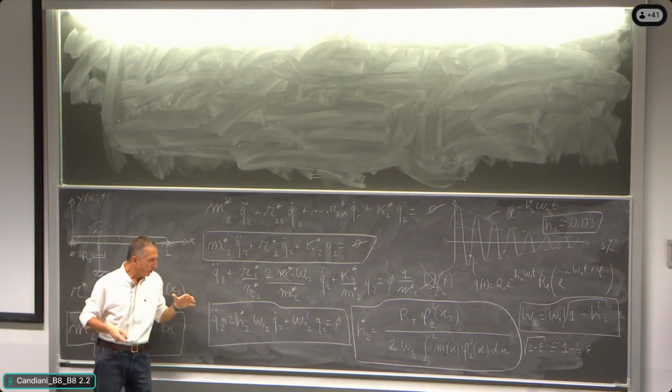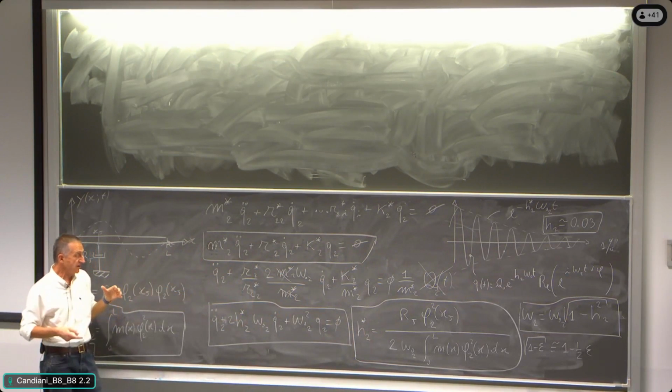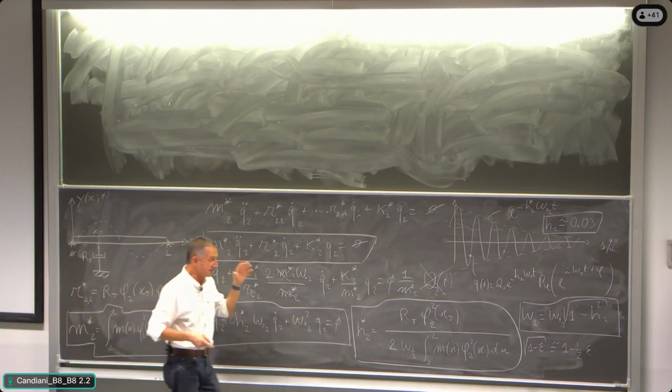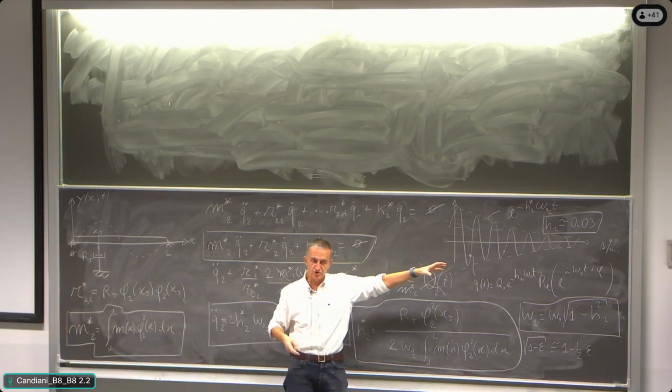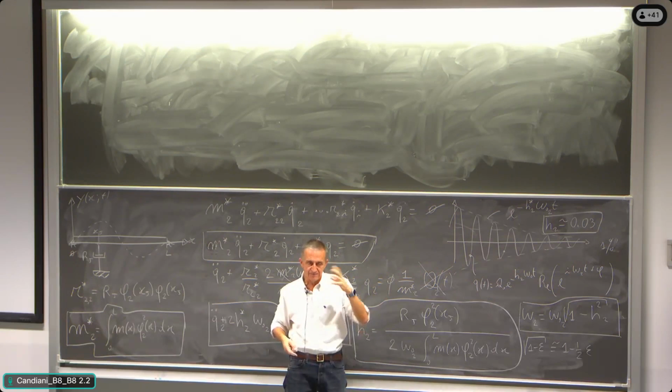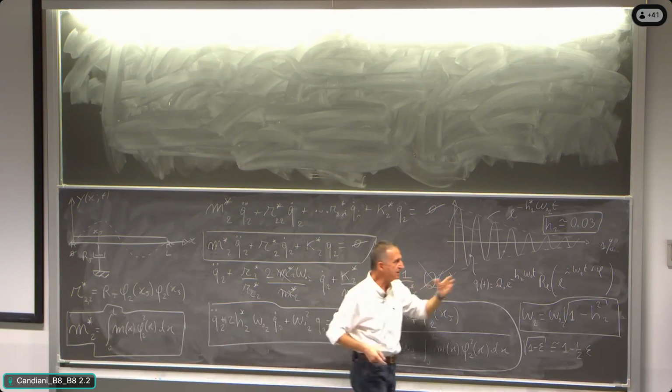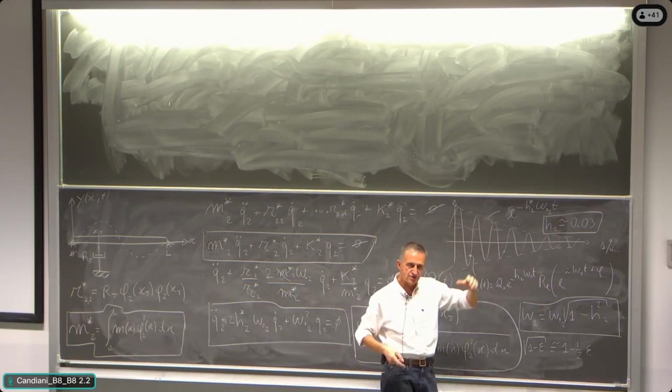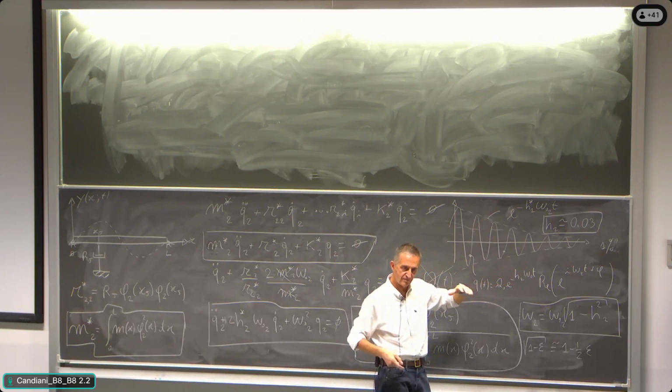And so what is happening, the systems that we are studying are systems that are vibrating, and the systems in which the level of non-dimensional damping is maximum some percent, 10%. 10% means that in one cycle, it makes 1/2 of amplitude, all right?